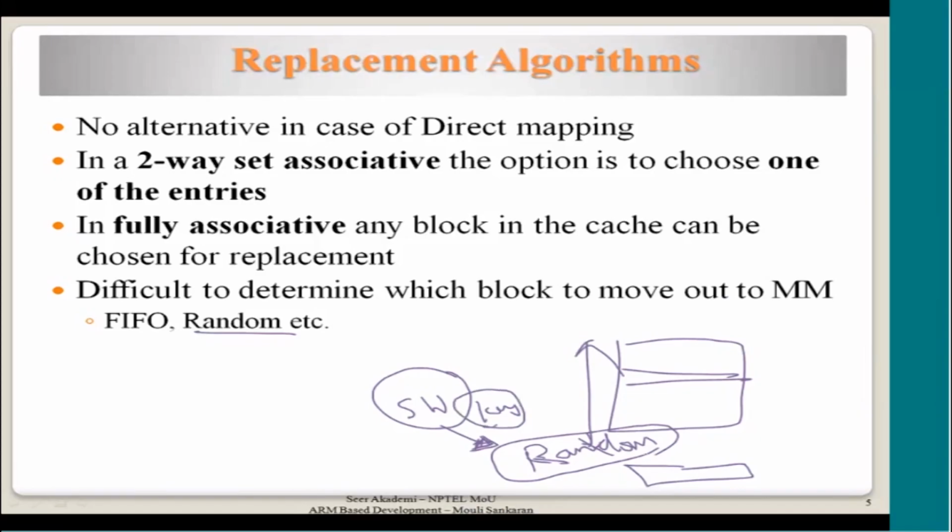So the randomness is also decided based on some hardware interface. Maybe a temperature variation in the chip, or a fluctuation in the clock. There is so much hardware logic used to bring in a random phenomenon and then generate a count, maybe 32 bits, or more bits, which is safer, so maybe 128 bits. Some things are maintained inside the hardware, and then it generates a random pattern.